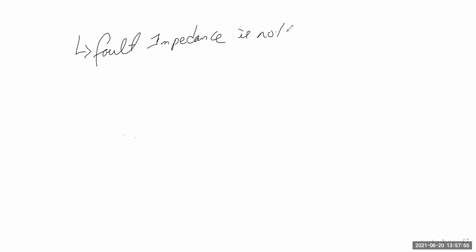We see that the fault impedance is not included. This point you have to note: in three phase, fault impedance is not included, so your ISC would still be V by Z.